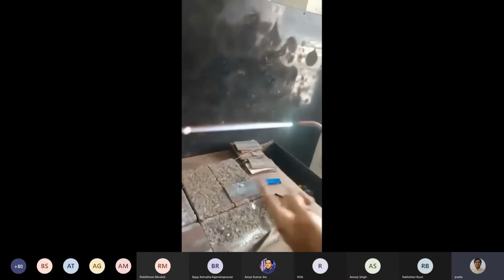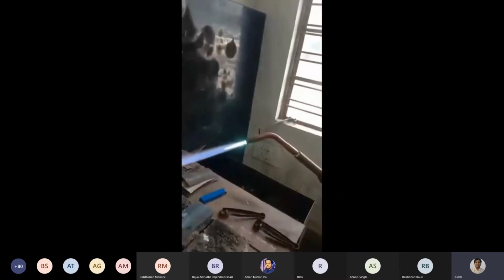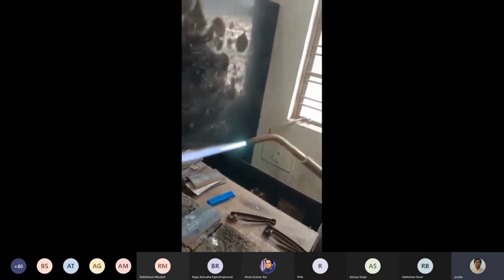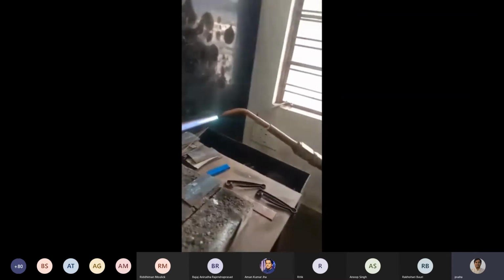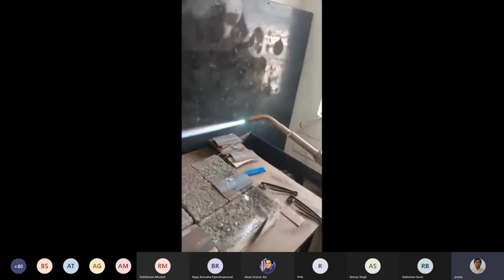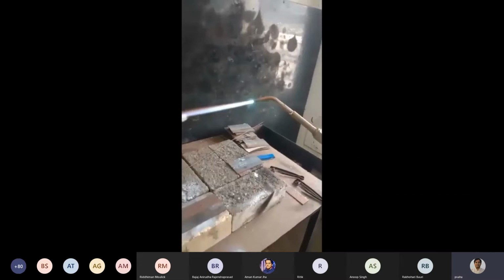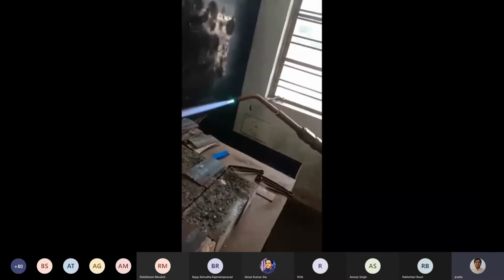In this flame, the carburizing flame, the temperature is about 3000 degrees centigrade. And this carburizing flame is generally used for high carbon steel welding. Now, if you again increase the oxygen, you see what happens to the flame. The acetylene feather gradually decreases in length. Now you see the acetylene feather disappear. Only two layers are visible, the inner cone and the outer flame envelope. And this flame is called the neutral flame.